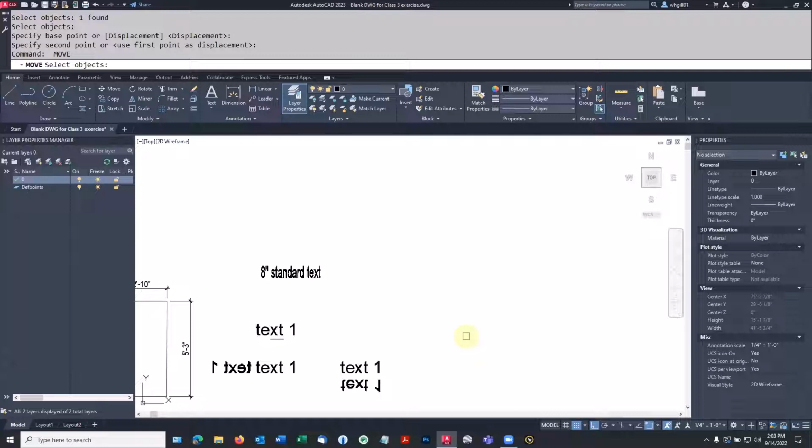But when you're doing either a bunch of drawings or a lot of text on one drawing, you don't want to have to keep fiddling. Probably most of the CAD drawings I do anymore have a style for notes, a style for dimensions, a style for titles, 3 or 4, half a dozen, something like that. Just keep it as clean as possible, so I have to think as little as possible about the mechanics of all that.